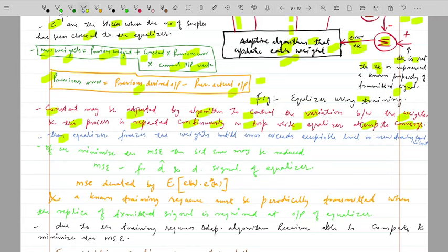Converge means that at the equalizer we get the desired output. Then the equalizer freezes the weights until the error exceeds the acceptable level or a new training sequence is sent. If either happens, the weights start updating again, the error process starts again, and so on.